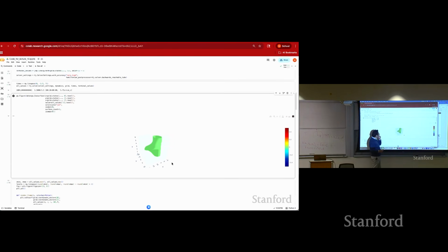So this is the zero-level set of the cost function as computed through the Hamilton-Jacobi-Isaacs equation. Which means that for those states for which J is negative, namely you are within this green shape, then you might end up in a collision. If you're outside, you don't end up in a collision. Why this weird shape? To illustrate how to interpret this result, this is basically the set of states for which J is equal to 0.